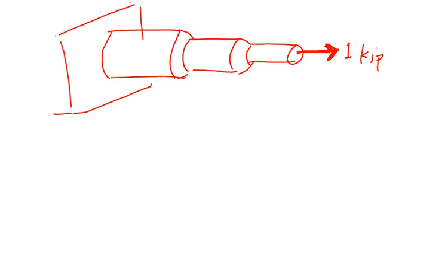This is now where we're going to get into this idea that every single mechanics of materials problem is first and foremost a statics problem. Okay? This is a static equilibrium problem first. And what that means is, okay, in a problem like this, you find your reaction first. So I have a fixed support on the left. If you think back to statics, this is actually a 2D problem. Okay. In fact, it's more or less a 1D problem. If you look at this, you just have forces in the x direction or in the long horizontal direction.